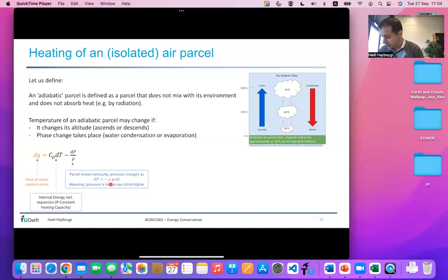It's like hydrostatic pressure. And so based on the conservation of energy, I have the Q term here. I have the internal energy and the work on the constant pressure process here. But there is another work that is to be done, which is by change of the elevation. And that would be related to change of the pressure divided by the density. We are writing everything per mass. You could also multiply everything by density, so you would get it for the density-based system. Here we have minus dp over density.